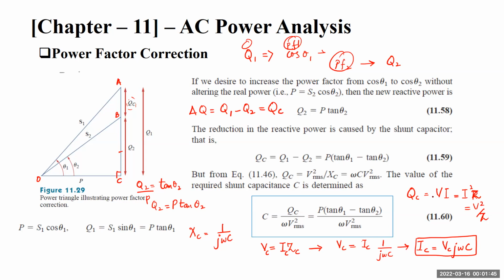So any of these formulas can be fine. So we have both value of IC and VC. So I use this value, and I've used a little different formula so that you may be able to see the values yourself as well. So QC becomes equal to VC multiplied by VC j omega C, and QC becomes equal to j VC square omega times C.